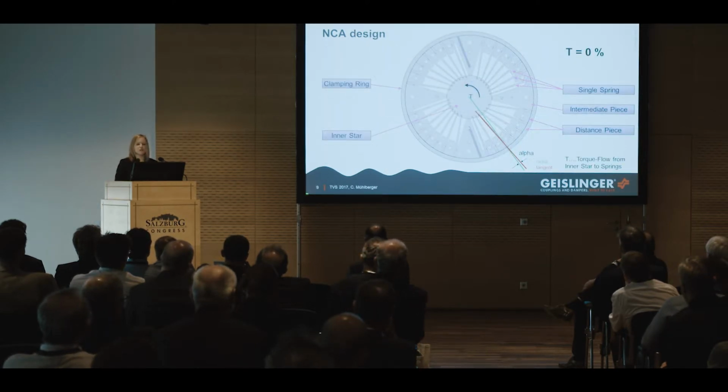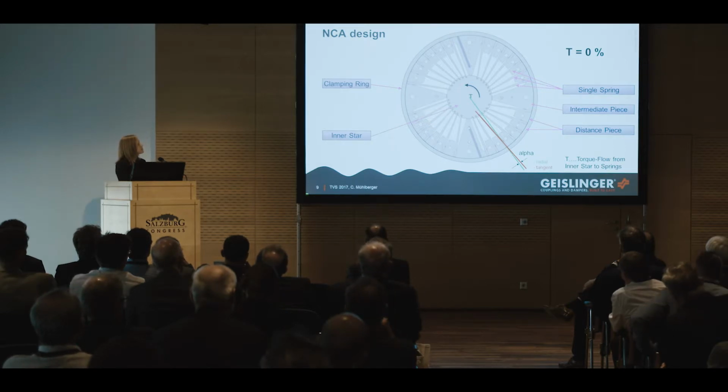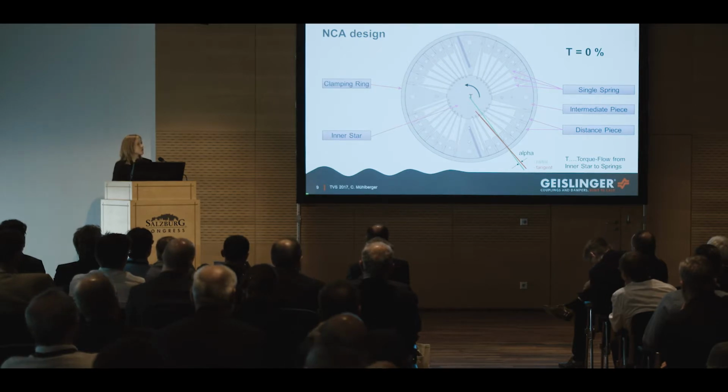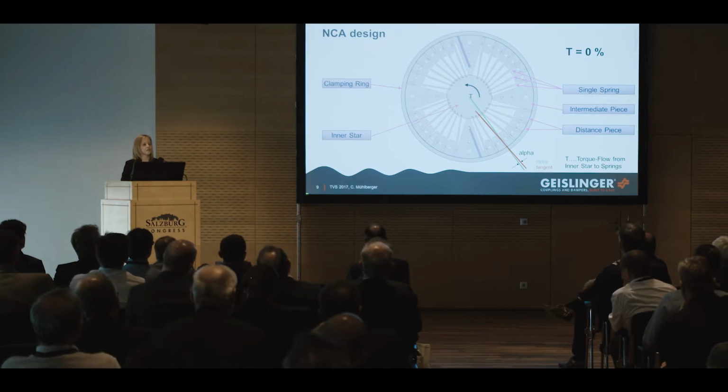So what is so special about this design? For one, we used here a single spring design divided by distance pieces. And this means we have already eliminated one main part of friction, because there is no additional friction between two springs themselves.